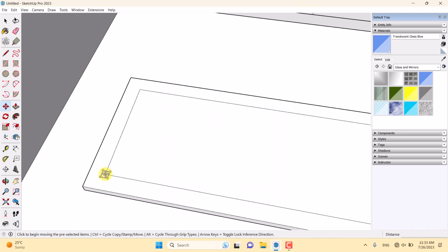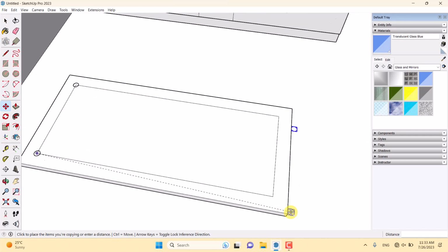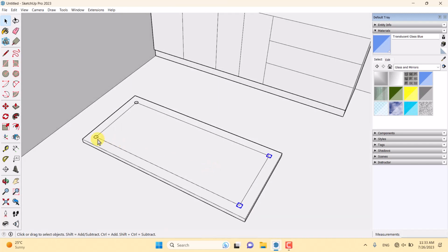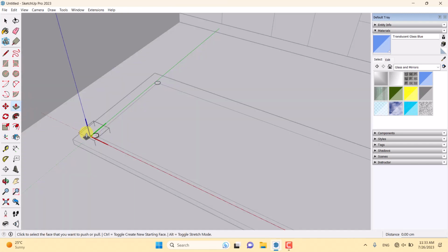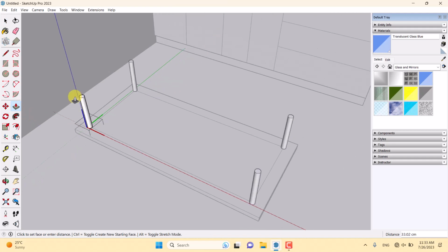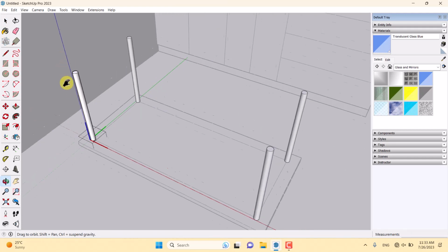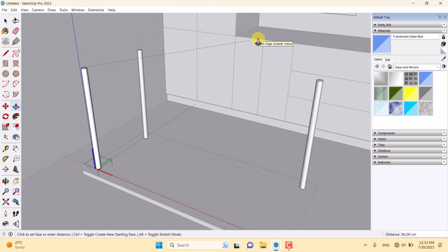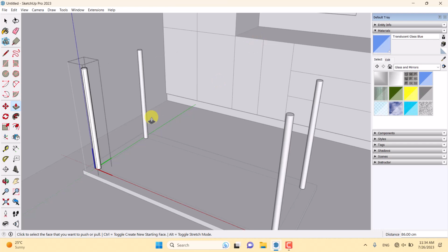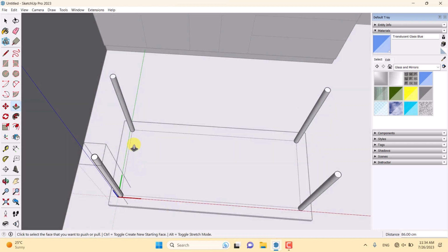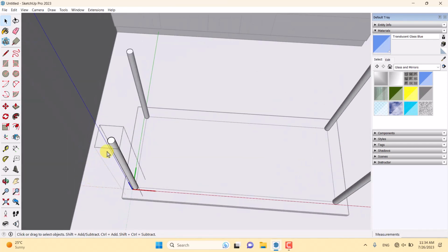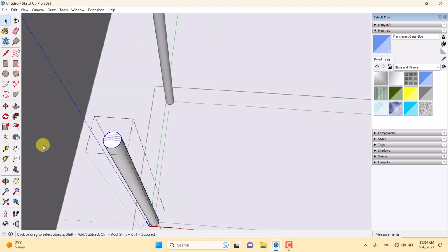So I can use this option in here. Now I want to apply some deformation to the holders. For this reason, I'm going to select these faces in here, use the scale option, and change the format of these table holders. For example, 0.6 in here, 0.6 in here, and another 0.6 in this place, and this place. As you can see, we convert some type of circle to some type of cone in here.